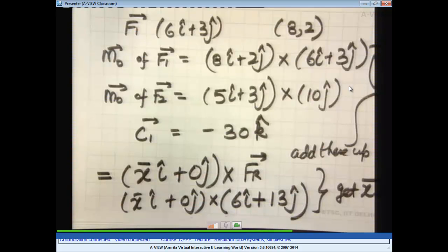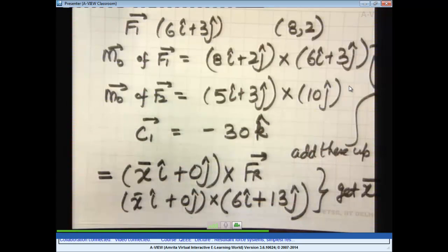And this is how we solve, where to find where does the equivalent force act. And you will realize in this problem, had C1 acted or not acted, the value of x bar changes. So the role of the couple C1 is to redistribute where the equivalent force acts. So this is for a planar force system. In the next class, I will look at parallel force systems.